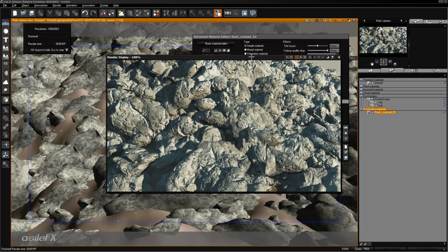One problem with rocks within Vue is when you have a world material on it, in a world coordinate system, and you have a lot of rocks grouped together, you end up seeing features from the rocks grouping together and kind of transitioning between them. So darker spots, and not a lot of variation between the individual rocks. Now, there are some ways to vary it by setting up material to be based on slope. That does help, altitude as well.